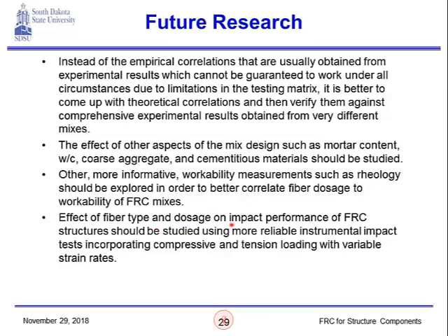The effect of fiber type and dosage on impact performance of FRC structures should be studied using more reliable instrumented impact tests, incorporating compressive and tension loading with variable strain rates. As I said, the impact test that we conducted is very qualitative in nature, so it's not very reliable, and so we recommend in the future using more instrumented tests where we can apply variable strain rates and then obtain some compressive and tension properties, which would be more quantitative in nature and would give us more robust conclusions.